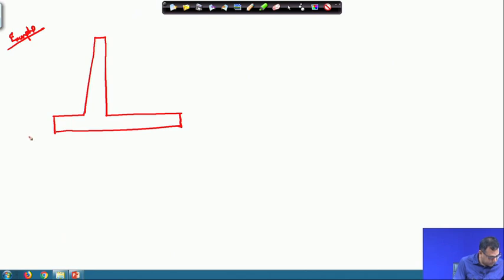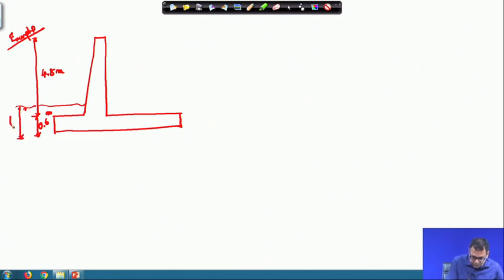Okay. So, again the height of this wall from here to here is given as 4.8 meter, and this one we have chosen for the first trial 0.6 meter, and the depth of this foundation I have again chosen 1 meter. Now, the width of this top portion is 3 meter I am taking, and this is an inclined backfill.